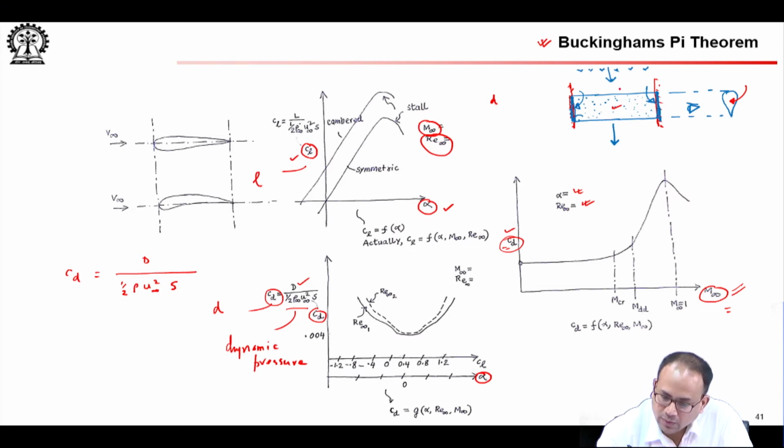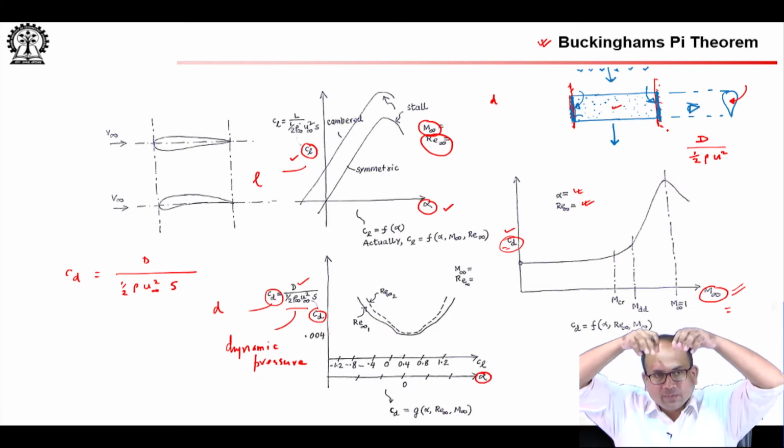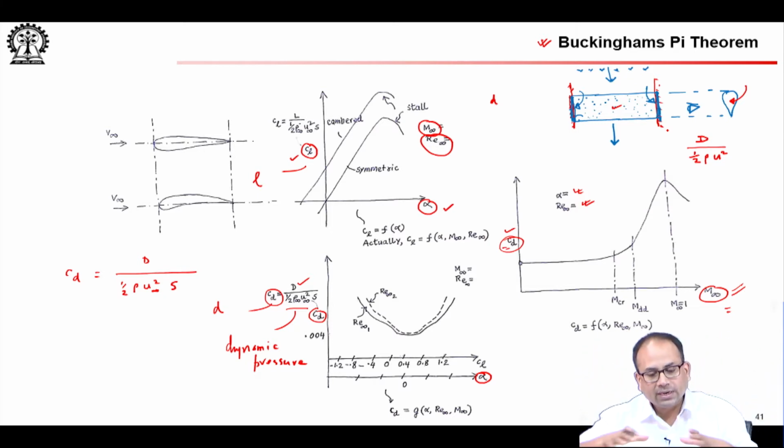So, you run this, you measure the drag force, say with some kind of a balance, and then you divide it by half rho u square. You can find these from your wind tunnel calibration charts, which tell you what regulator setting gives what velocity in the test section. And S is the reference area for this kind of test. For a finite wing on an aircraft, you look from the top and find the projected area of the wing, extending it into the fuselage. That is your reference area.